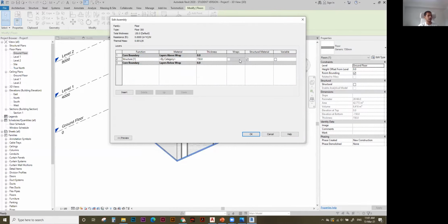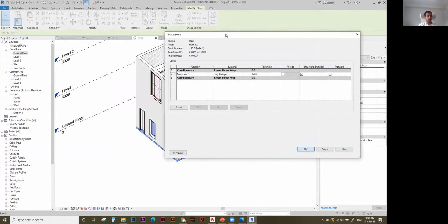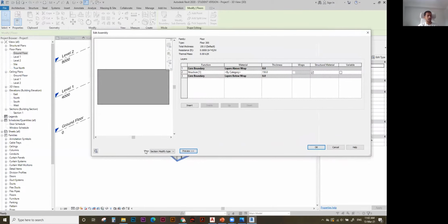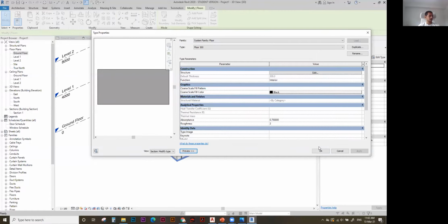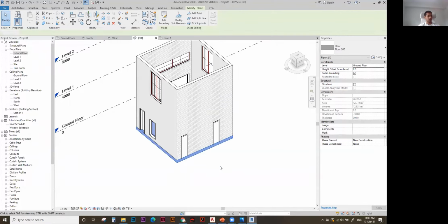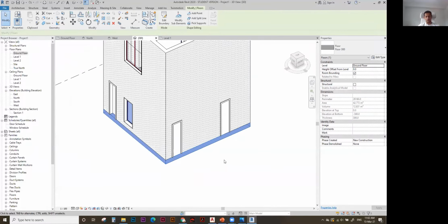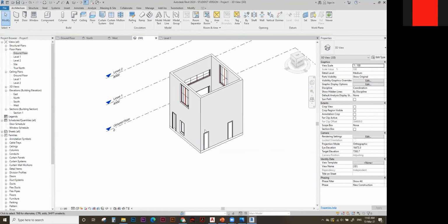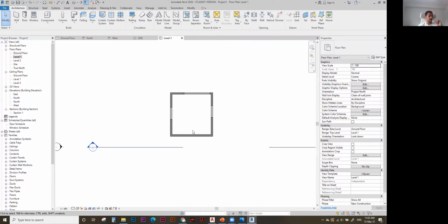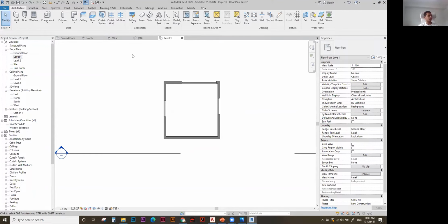And inside that, we've got a similar option like we saw in creating a wall. So I'm going to go inside structure, and a very similar panel opens up, but this time it's the floor slab. This is like the section cut of the floor slab. So I'm going to change my thickness to 300 and hit OK. And now the thickness of the floor has become 300, and that's also updated in the model. And now that's the ground floor that we've created.